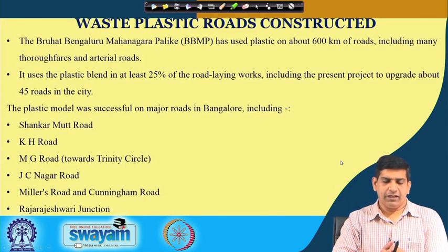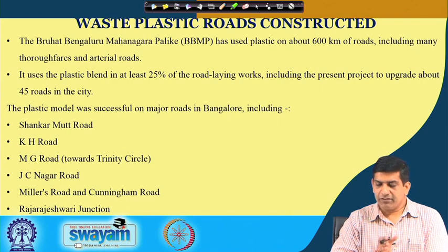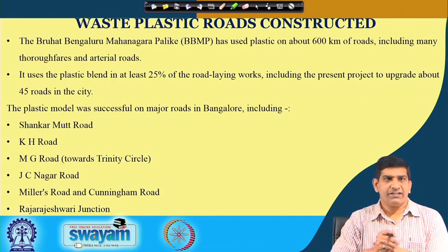Waste plastic in Bangalore also is being used. BBMP has used plastic on about 600 kilometers of road, including many thoroughfares and arterial roads. It is also used as plastic bitumen in at least 25% of the road laying works, including the present project to upgrade the 45. The plastic model was successful on major roads in Bangalore, including Shankar Mutt Road, KH Road, MG Road, Shivajinagar Road. These are just to give you an example that this is already being done in India. It's not new.